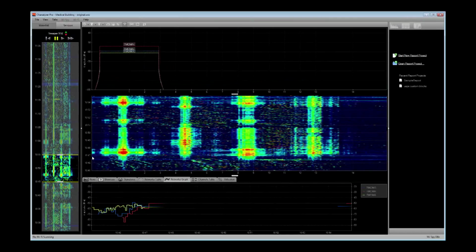So if we were to look at 1047 in the amplitude history view, look at this. Right around 1047, we see something start. So this is our earthquake. We notice something like an earthquake comes on. Something starts transmitting. And this is immediately a red flag. So let's turn on the color by utilization.